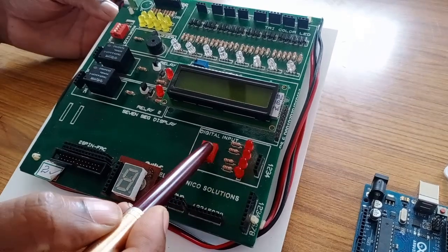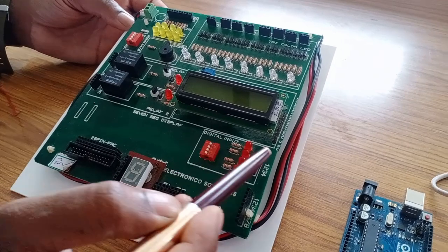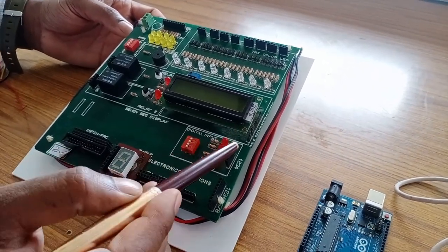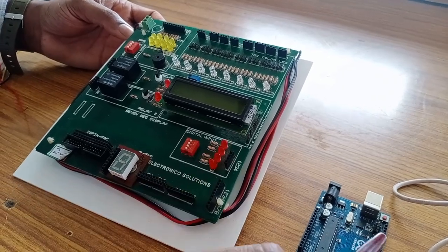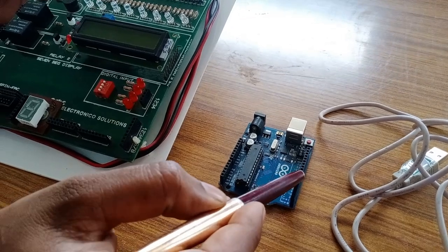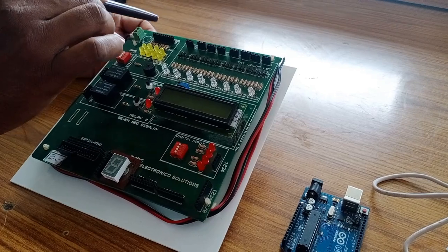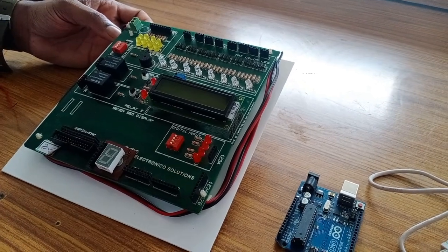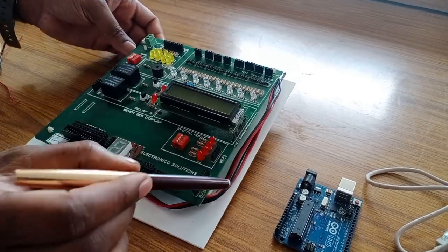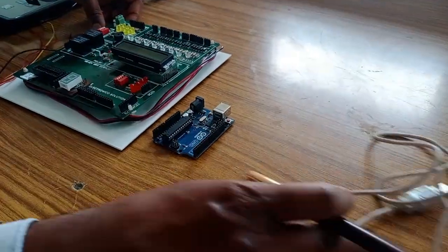Here you won't find two terminals on the dip switch, you will find only the output terminal. From the output terminal of the switch, we need to connect to pin number 10 on our Arduino hardware. Then from pin number 12 on the hardware, we connect to the LED. I hope you remember the connection we established in our Tinkercad software. Before making the hardware connection,